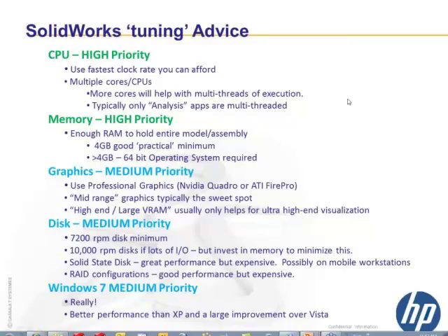Okay, and I know I'm running tight on time, so let me just finish quickly. Graphics, I would recommend professional graphics, so the NVIDIA Quadro or the ATI FirePro. These are going to be certified by your software vendors. I find the mid-range graphics is typically the best sweet spot. You don't really need to overpay for the high-end graphics. It's usually got features that you really can't use.